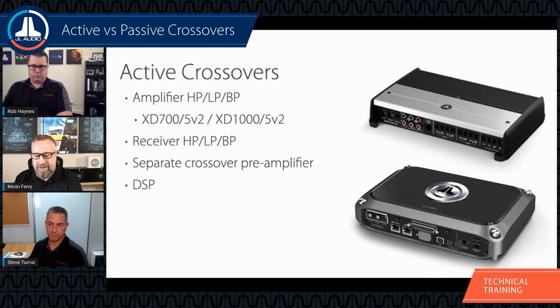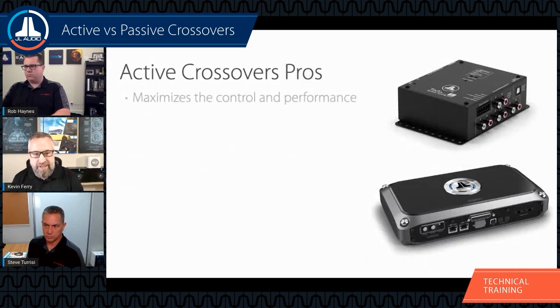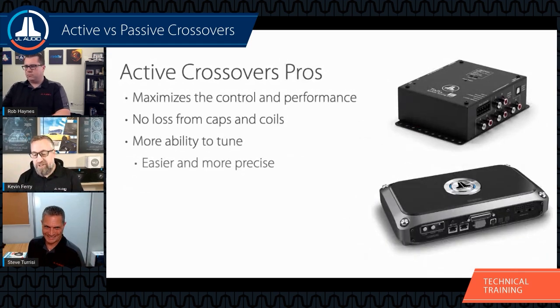Yeah, I don't either. And like I said earlier, a lot of times they aren't saved on non-volatile memory. So if the car goes dead or something like that, then you lose all of those settings. Or if they're on an amplifier, even a DSP amplifier like a VXI or MVI, they have built-in non-volatile memory. Those settings are all going to be saved and stored in there. You don't have to worry about that at all, so it makes it nice and easy. Try to utilize what's in the amplifier or your DSP. And like Steve said, leave the receiver flat, not just for high pass and low pass filters, but for most of the settings on there too. I know a lot have bass boosts and all of that stuff that can get crazy on you. We'll save that discussion for another train.